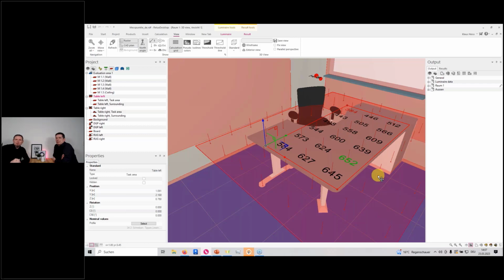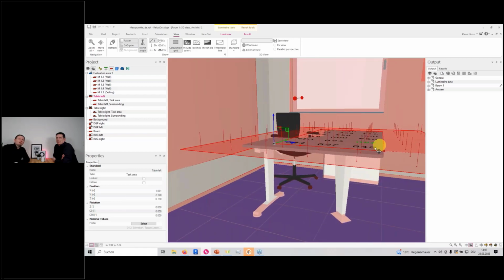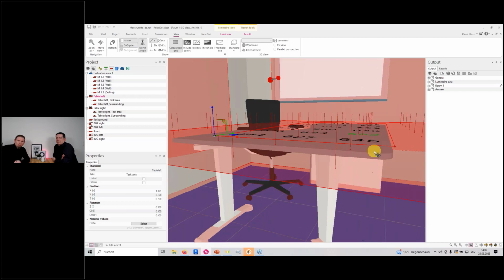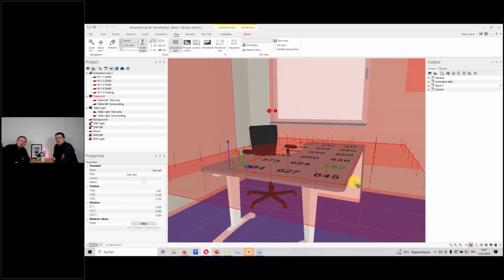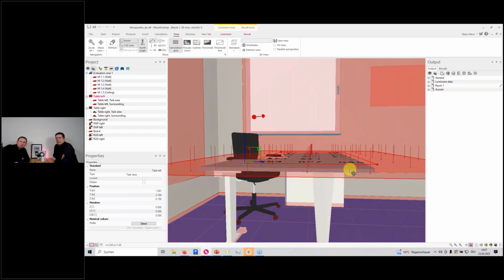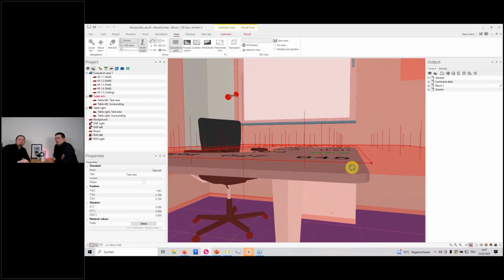We have just single points to measure, and not just single points. We also calculate and measure with a direction of measurement. So it's a huge difference if you measure the light from up to down, straight from one direction, or from different directions. This has an impact on the measurement, as it also has on the calculation. A good example is here, where we have horizontal points. You can see here the small vectors, the small lines, which demonstrate the direction of measurement.